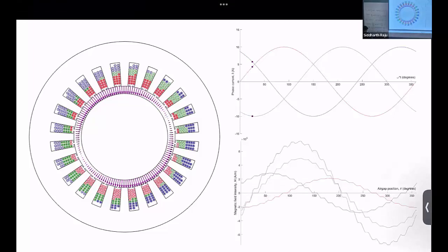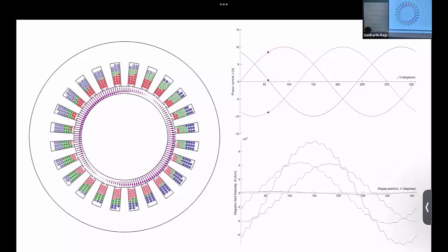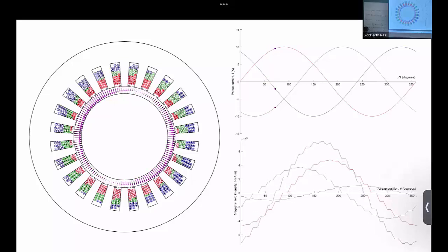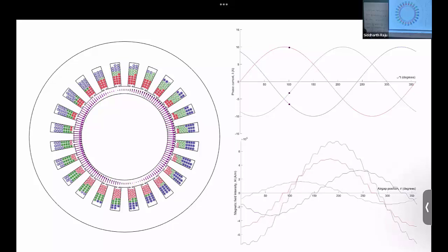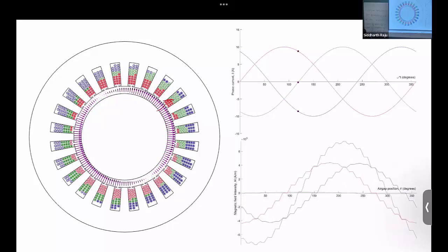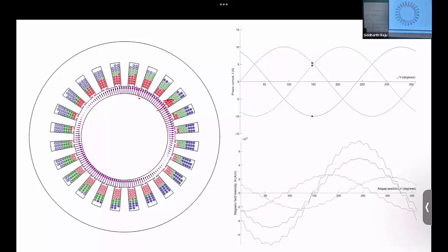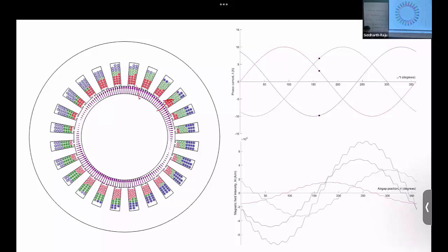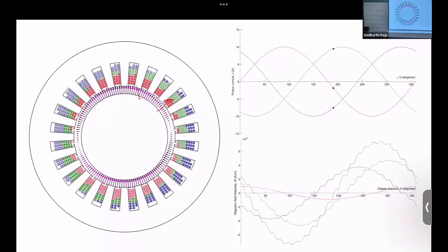All right, so this is the diagram we have already seen. We have our three-phase motor. The whole B field is rotating, and the space vector that I just drew is basically capturing where this peak is. And if you see, Jonah, this answers your question. At any given time, the peak keeps moving. So space vector is basically capturing that peak. So it doesn't have theta information as such. The time is the theta information that is being captured.